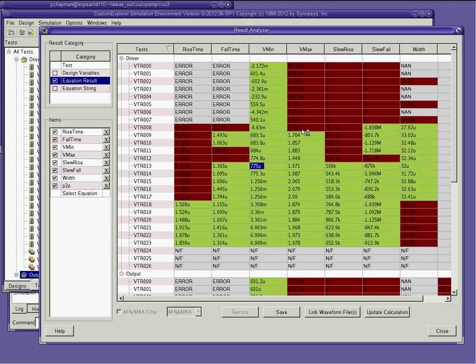After you've set up your measurements, you may well want to define a whole range of tests that will be run across perhaps a different set of load conditions, voltage conditions, and the like. If we come here, we find a little pull down that lets us find parameters that are present in the netlist that typically are the ones that we'll want to vary across the tests. So I'm just going to type in a range of values that we might want to consider.